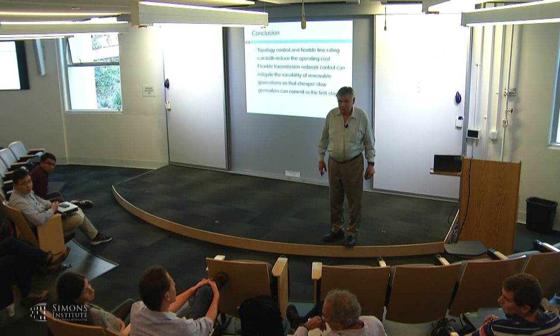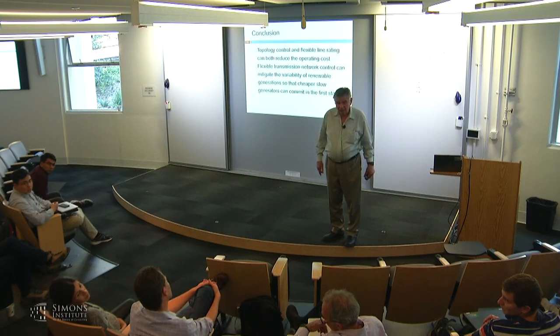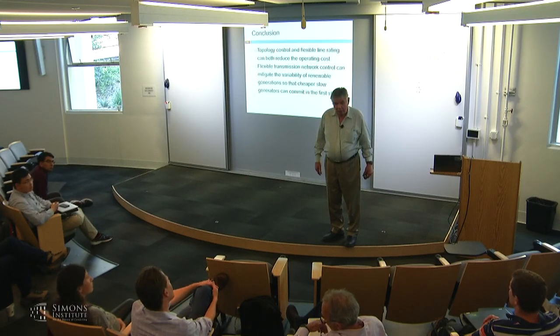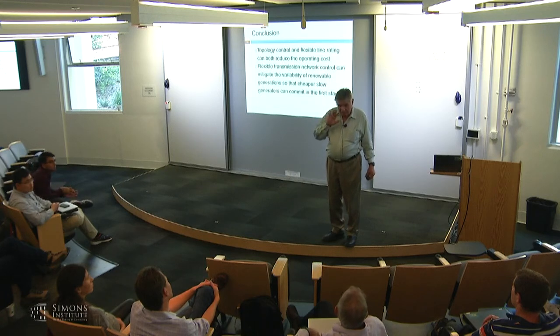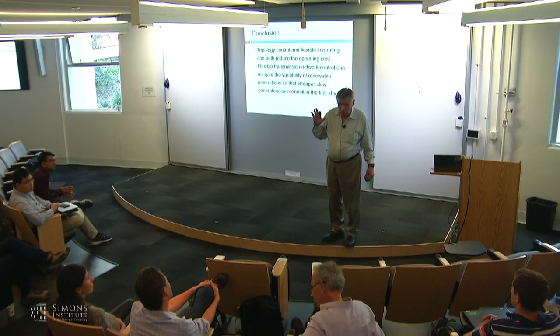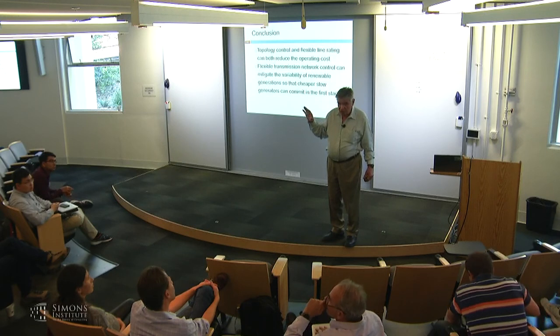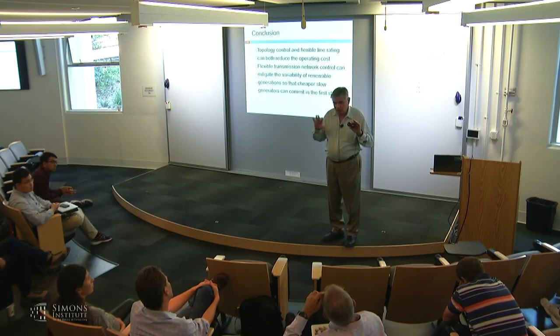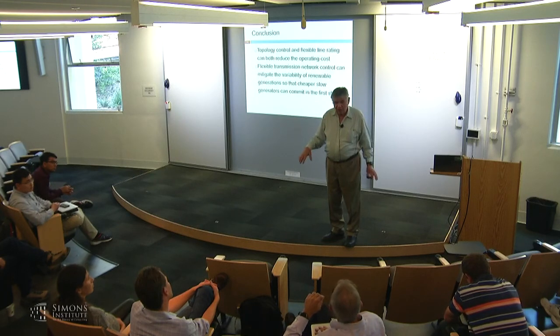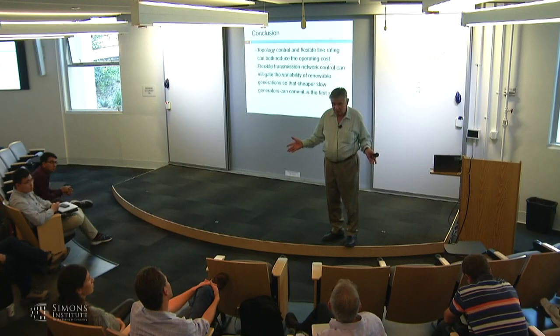Yes? How would you compensate the transmission right owner if you switch off their line quite often? Well, the ISO is basically controlling the network. They can give them orders. The only problem that line switching creates, and when we did our RPI project, that's why we backed off from the idea of doing transmission switching for economics, is that it screws up the forward transmission rights market, the FTR market.